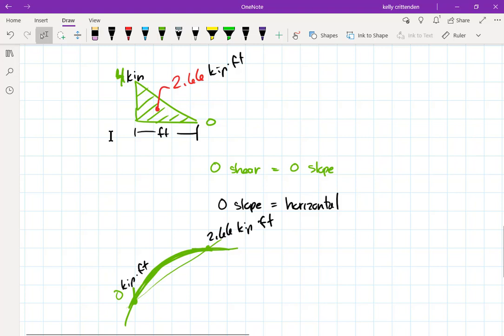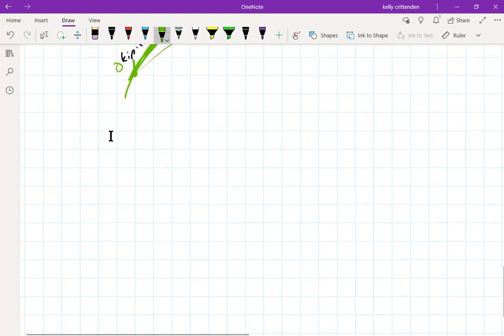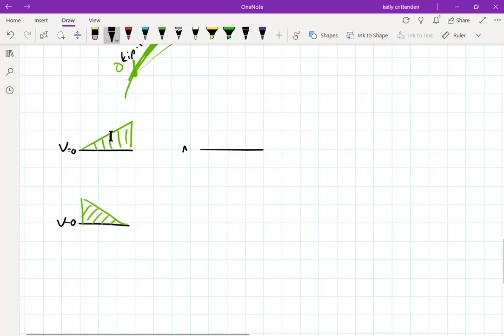So let's say the triangle backwards split. Yeah, so curvature would be the opposite? So let's look at the 4 different options. So you have, this is your shear, B equals 0. And for the positive ones, there's this option and there's this option. So in your moment diagram, well, we won't draw that, but in your moment diagram, you know that in general, both of these have positive slopes because they're positive shears. You just don't know the curvature.